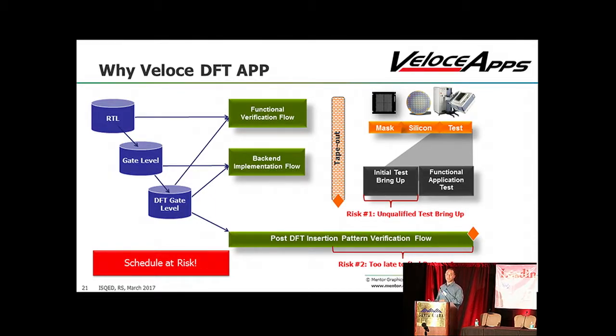Then comes the gate level. It's usually a few months later on down the road. Now the DFT can actually begin. So all of that time that could have been spent bringing up DFT now gets pushed out. Finally, once you have your gate level with all your scan inserted logic, then you start your simulations.